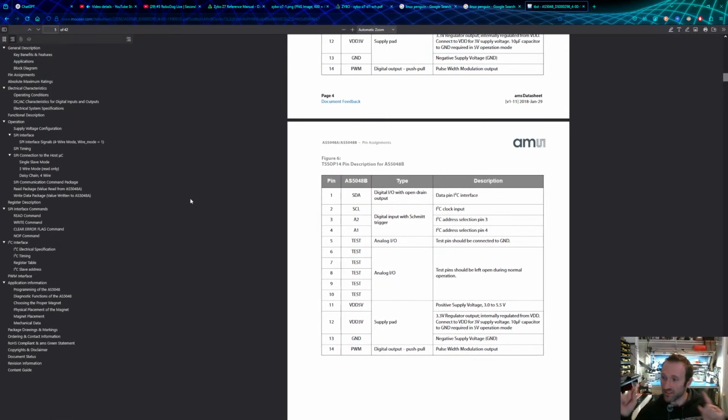I would suggest if you do something like this, do calculations first, to see how heavy you think things will be, and if you have the properly spec'd out motor for torque at least, and how much you need to ratio up the torque with the gearbox.